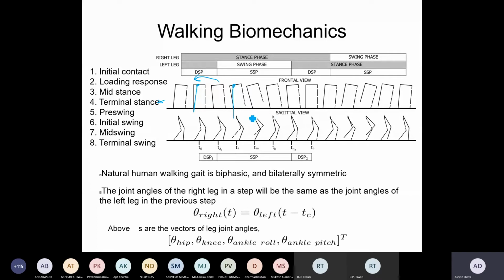Then the leg goes forward, and contact is made. Now you're in a two-legged stance, and then again the body moves in the other direction. Again the CG is on the leg on the ground, and then the other leg goes forward. So for a two-legged system, the gait diagram is two leg, one leg, two leg, one leg, two leg, one leg. That is the gait diagram. That's how we move forward. This is the front plane.